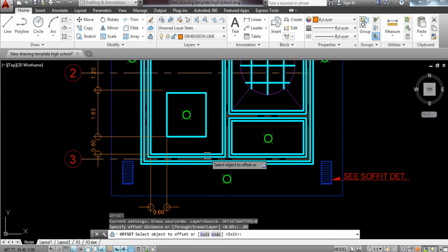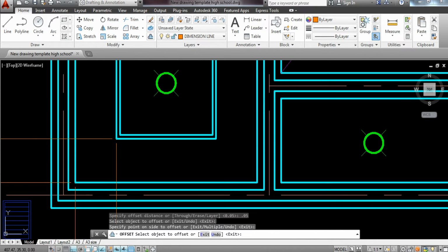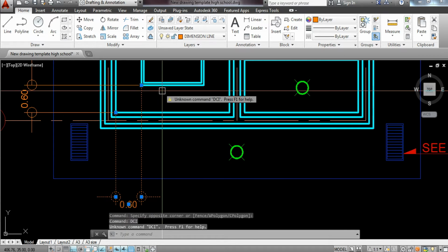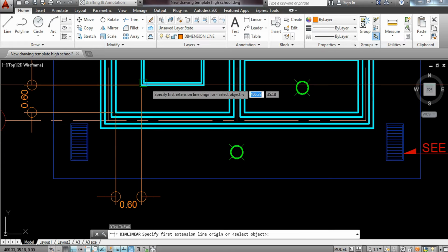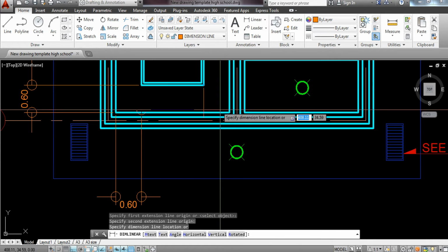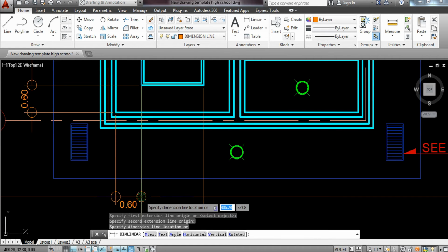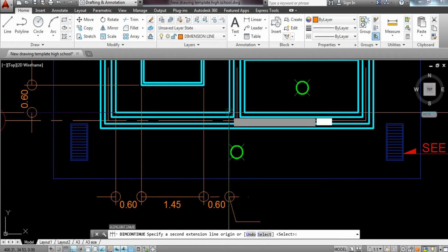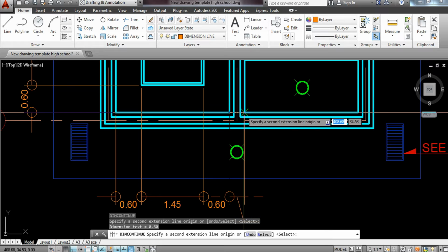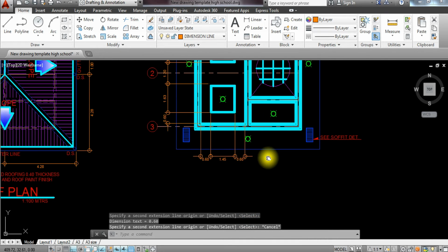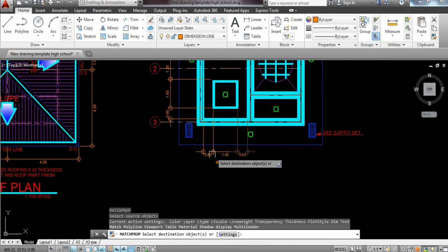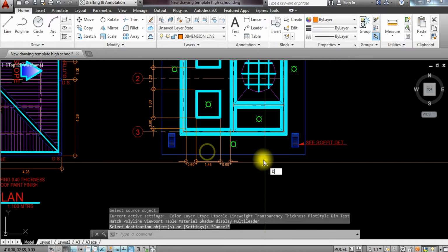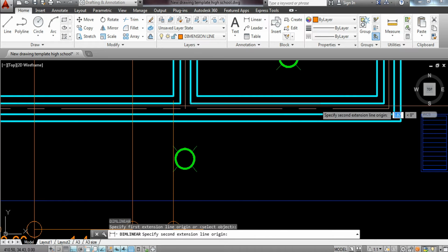So offset 0.05 for the cornice, or what we call the molding, and then highlight this one, DCO or this DLI, click, drag backwards, DCO, dimension continue, then this one. So copy, match the drawing here, here. So DLI, continue here.